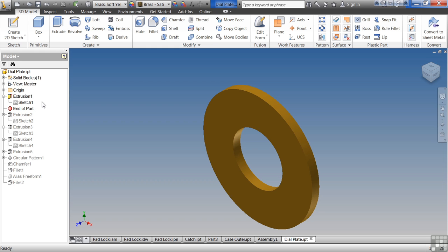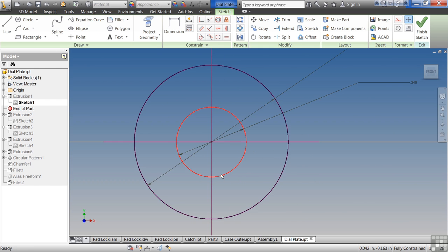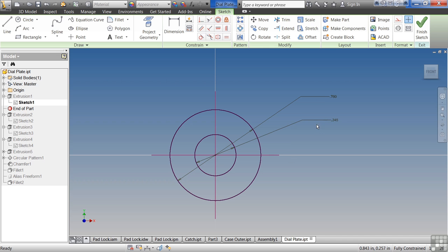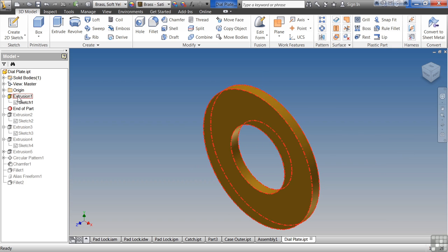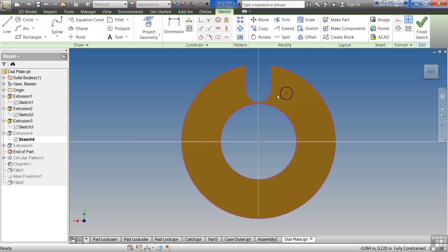So to create a parametric model, here's kind of the process. We start out with a sketch, a simple 2D sketch that we give information to. We tell it, this is how big I want this. We extrude this out as our base feature. Then we add additional features based on secondary sketches. What this means is this sketch has relationships to the other sketches that are already there. We don't have to redraw them from scratch.